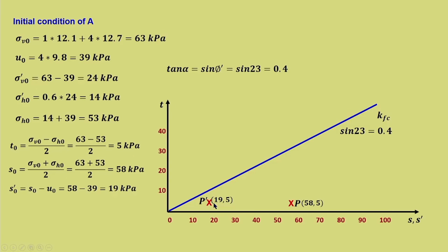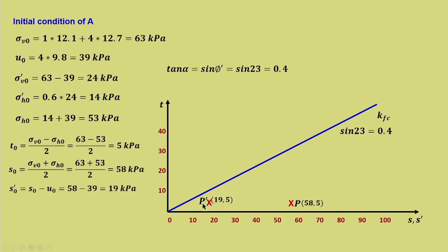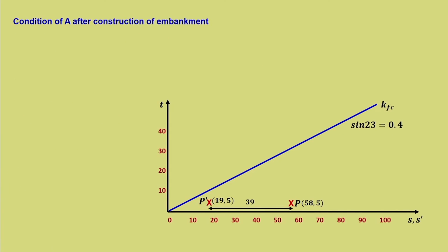You can see that the initial point itself is very close to the failure line. So, you can make some judgment right at this point: there is not much allowance for failure, it is very close, and the factor of safety is substantially low. In the last lectures we have seen that when it is close to the failure line, the factor of safety is less. So, accordingly we can easily make out that the safety margin is quite less in this particular case. This is 39.